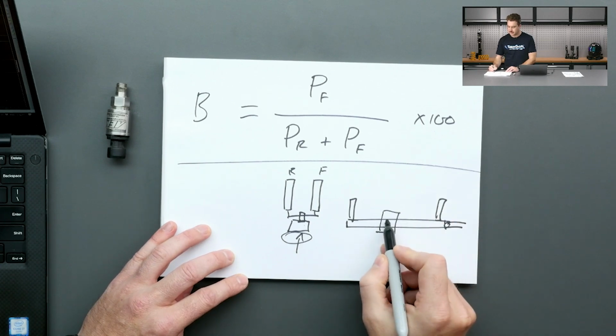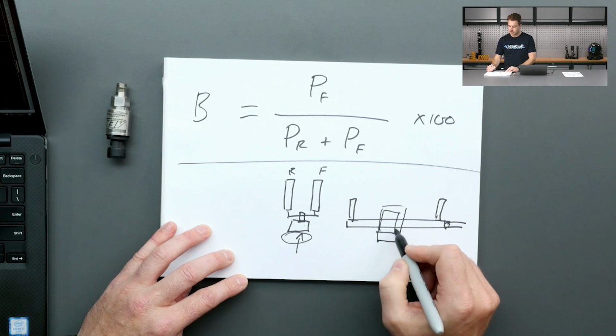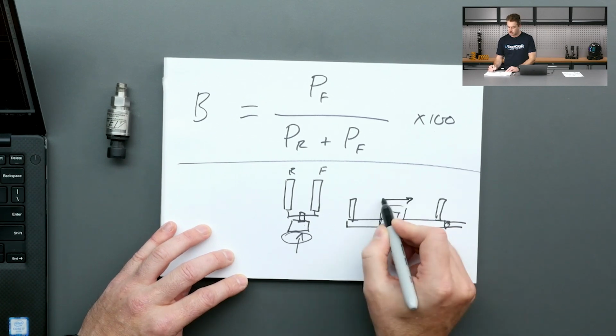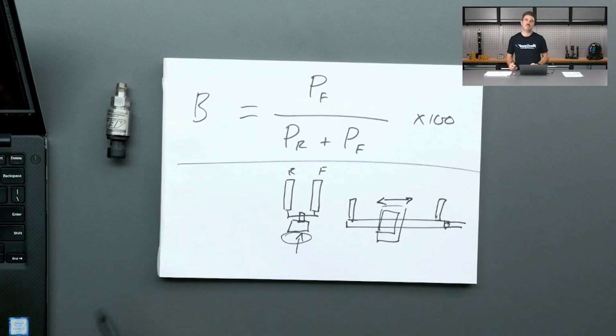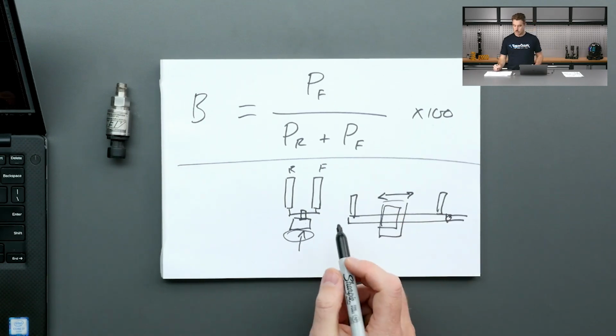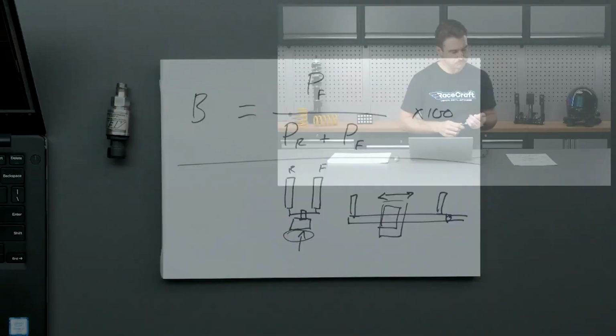The idea is that as the connection between the brake pedal and the trunnion bar moves along, if you move it more towards the front, you're going to have more of that mechanical force proportioned to the front hydraulic system, and if you move it to the left, you'll have more on the rear hydraulic system. So that's a little bit about how that bias bar adjustment is working.